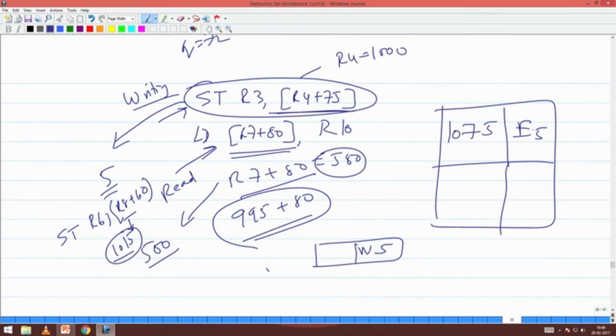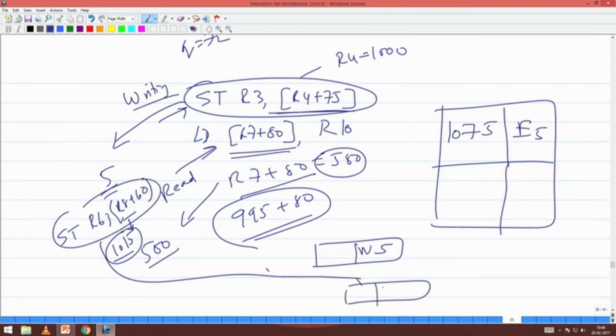Suppose this store is currently allocated to execution unit 8. Then you just make this E8, that is all. We also handle two fellows writing into the same register R1. All the subsequent instructions beyond that should do this. But when you are writing back, the reorder buffer will see that it is committing the latest value.